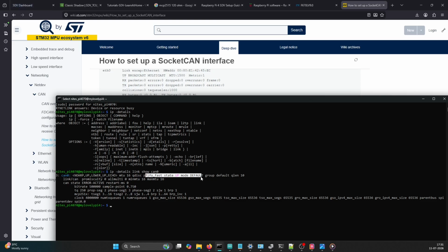You should also see this kind of information once you run this command. It means your network setup is completely correct. Now, at least from the Raspberry Pi and MCP 2515 side, your communication is enabled. If any messages are coming on the bus, you will definitely receive them over here.